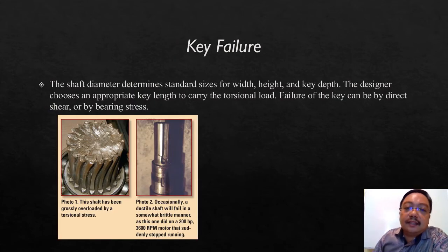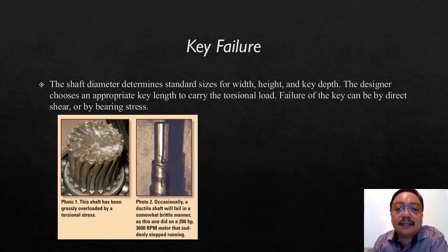The shaft diameter determines standard sizes for key width, key height, and key depth. The designer chooses an appropriate key length to carry the torsional load. Failure of a key can be direct shear or direct bearing.